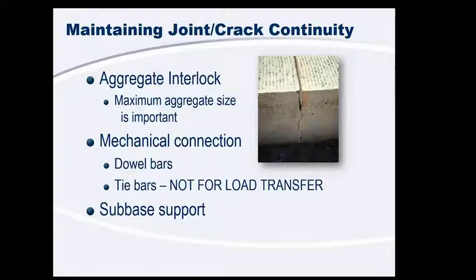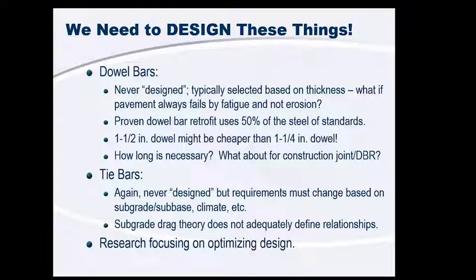When you talk about dowel bars, we'll actually talk about dowel bars as we go through. Additionally, sub-base support is not typically what you're relying on, but it can contribute some to your load transfer. However, I would warn you that messing around with your sub-base support for the sake of load transfer is definitely not something you want to do. You'll end up creating consequences for yourself that you shouldn't have to deal with.